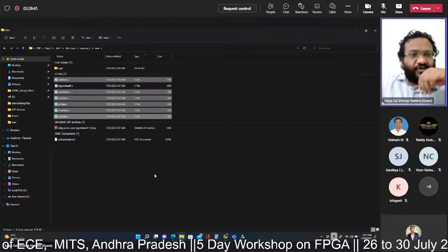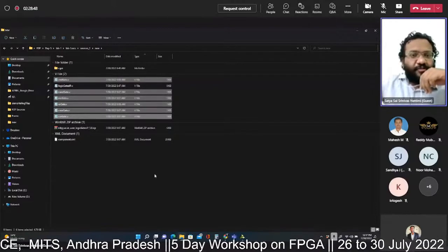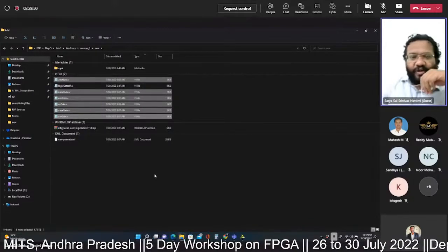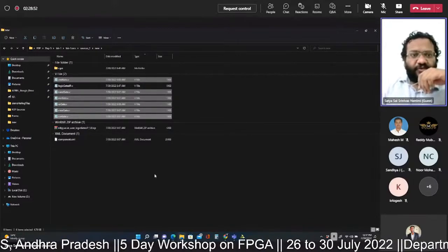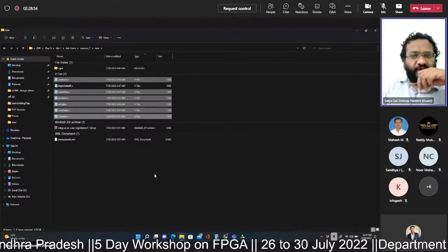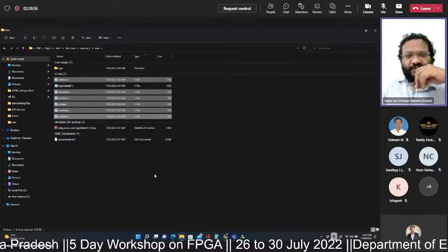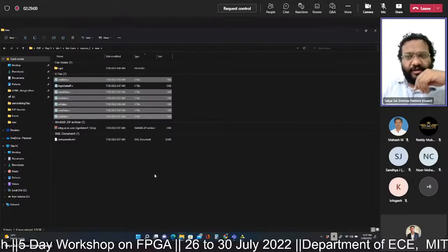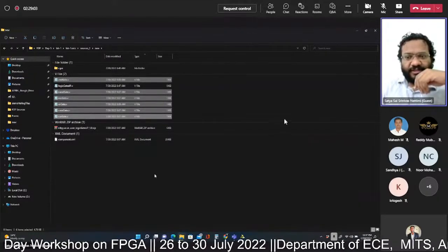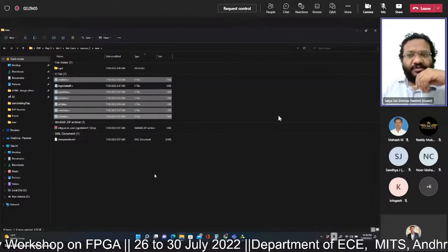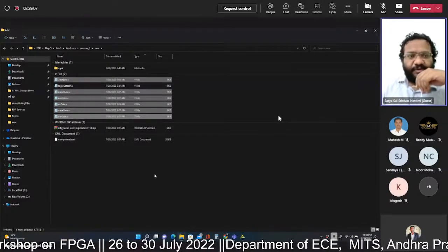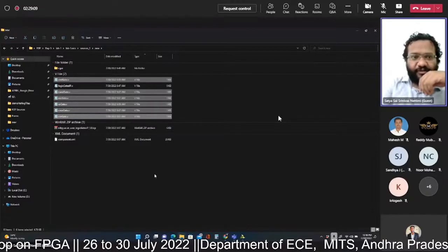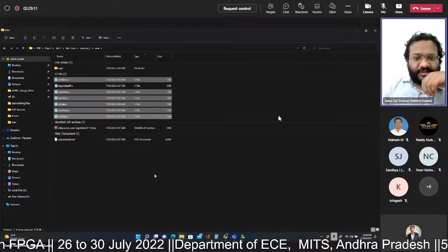Why? Because an inverter has only one input, one output. But since we are making an IP with 2 inputs and 1 output, we cannot put it over here. We need to use the concept called dynamic input ports. That is a little bit complicated, so I'm skipping it as part of this FTP. To keep it very simple, I'm using only 6 gates.